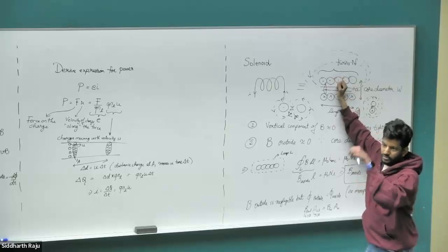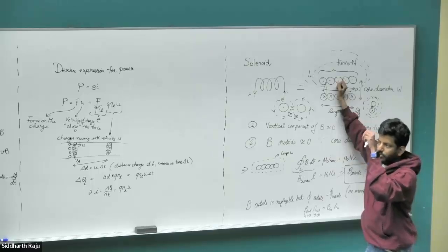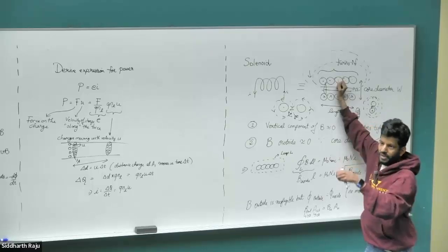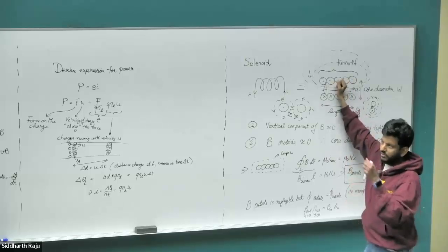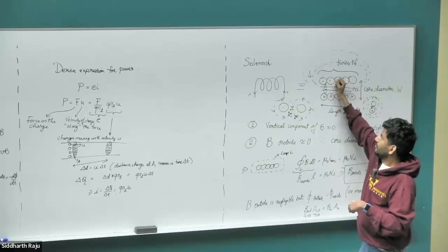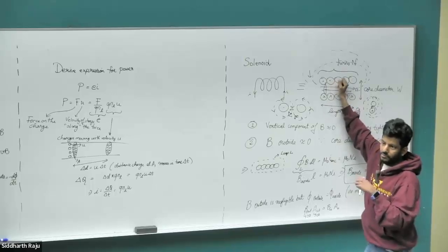Similar to when you have two resistors in parallel, the current would prefer to go through the path of least resistance. When we have an iron core inside, it creates the least reluctance, a term I will introduce here. So the magnetic field lines will try to go through that pathway.